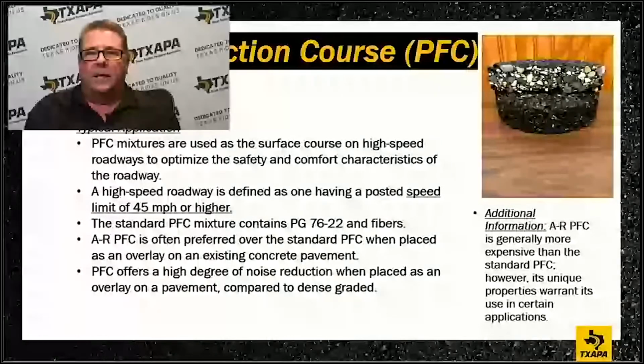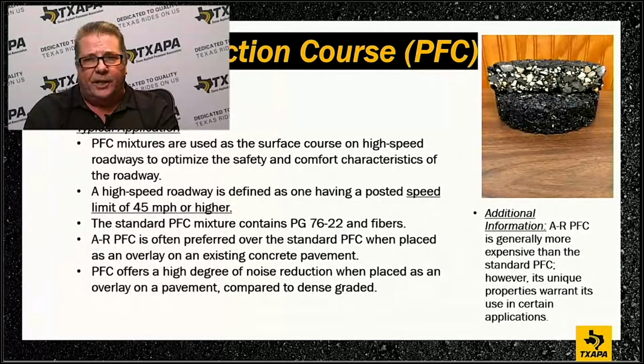And the reason for that, again, is that it's engineered. That's an engineered pavement. 76-22 with that aggregate structure is going to give us something that lets the water flow through and yet gives us a good surface to ride on. In other words, it reduces wet weather accidents, increases skid resistance, and decreases the noise coming out of it. Overall, it's a great product, but you can't use it everywhere. It's not a silver bullet. You have to engineer it for the correct usage.